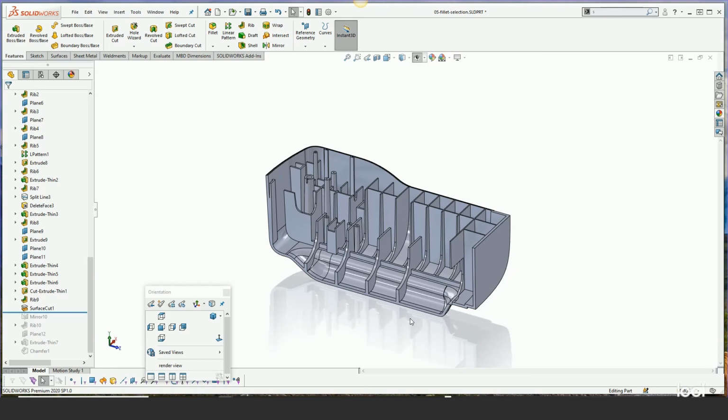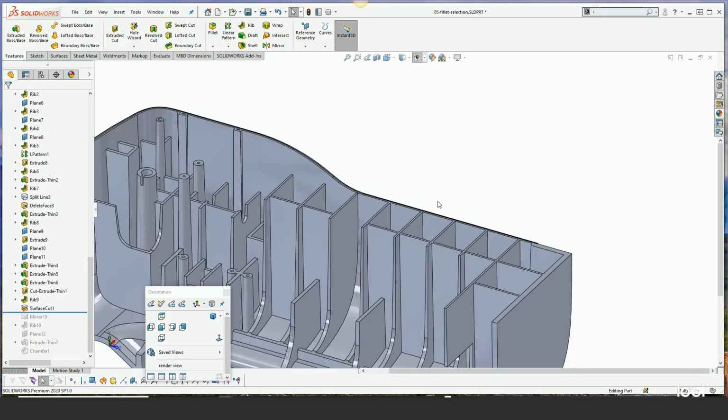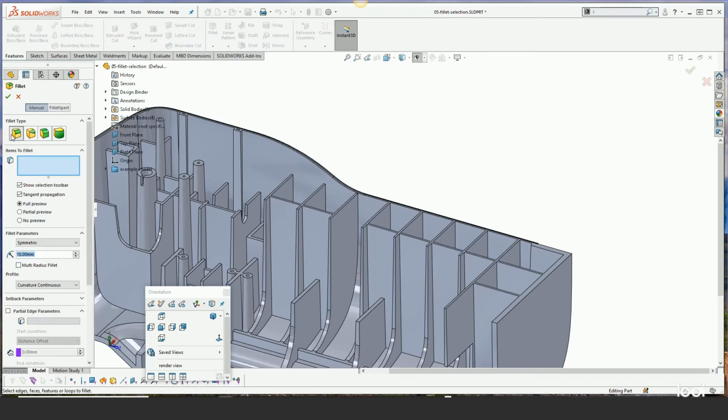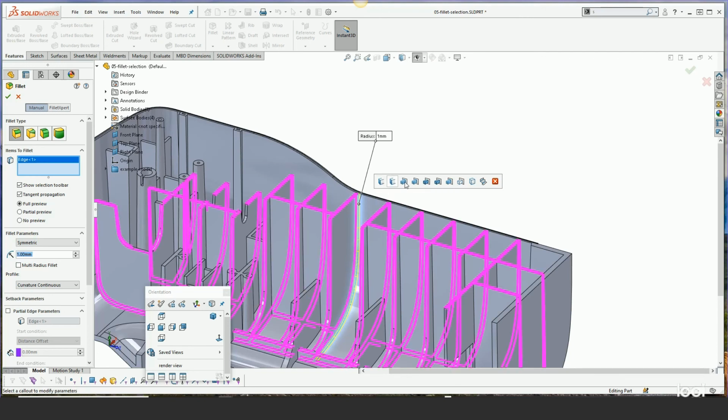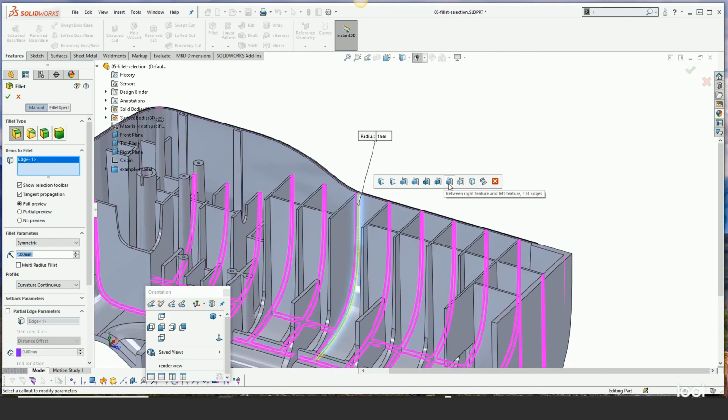And this is important for this selection feature because when we go in and start selecting to use the smart selection, if you see any other fillets along that face, it's going to pick edges you probably don't want. So what I'm talking about very briefly here is I'm going to do a constant edge fillet by 1mm and pick this edge, and immediately I get a helper. And when I get that helper, I can go and look for faces that I want to fillet all at once. It's kind of like a super macro. And this is a very valuable tool when you have lots of features like this.